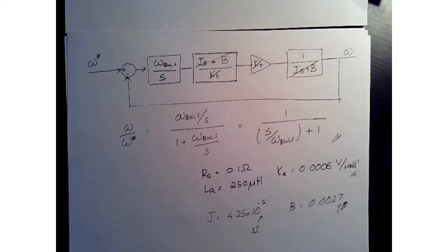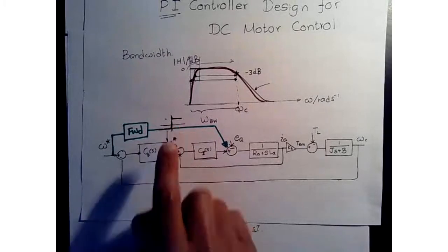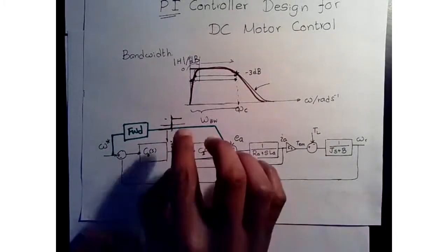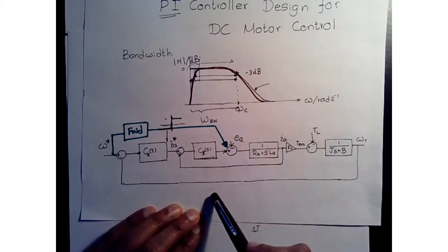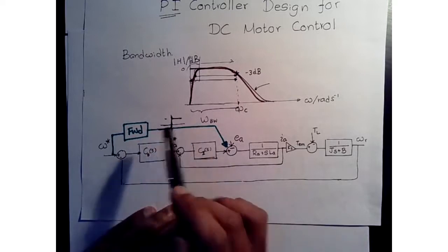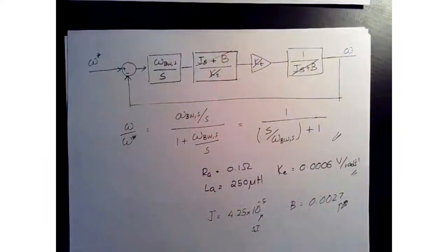See if your responses are acceptable, right? And then try it without this limiting function and with the limiting function. What does it do to the system? Because having this current limiter will make your system nonlinear. Okay, so that's why we design it without the limiter and then we add that later. So one exercise you can try is to simulate that. Feel free to share your results with me, and we can even discuss them in detail. Okay, good.